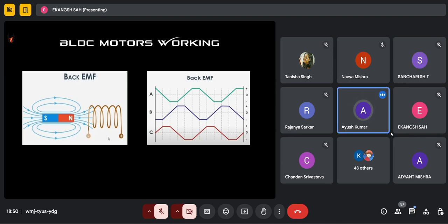The left diagram shows how the back EMF is generated. At a time only 2 motor windings are active and one is neutral, and that neutral motor winding is used for the back EMF detection. As the permanent magnet of the rotor rotates, the magnetic flux linked with that motor winding changes, which generates a current in that motor winding.